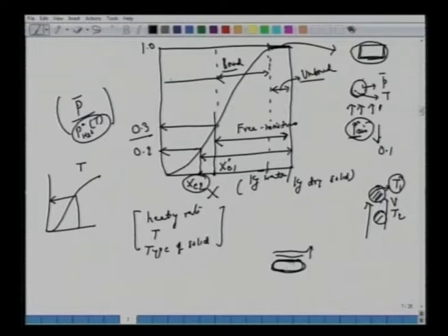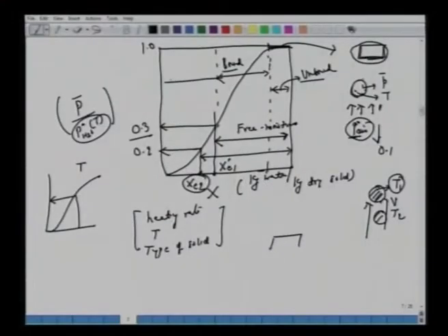Below this, now we are talking of dry patches. Okay. So what we are saying here is that to begin with, the solid has a film of water over it. So the partial pressure is the same as the partial pressure of pure water, and then patches of dry surface start appearing, and then we have a different type of moisture, which we call bound moisture. Okay, so we use three terminologies here. One is free moisture.